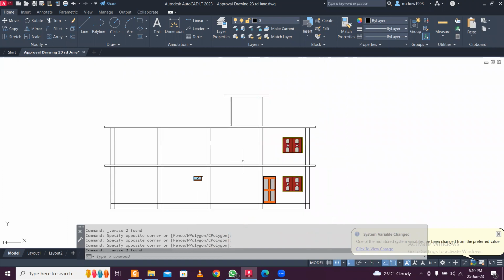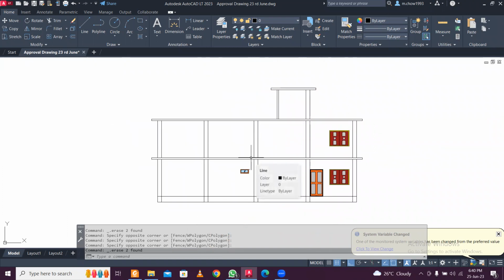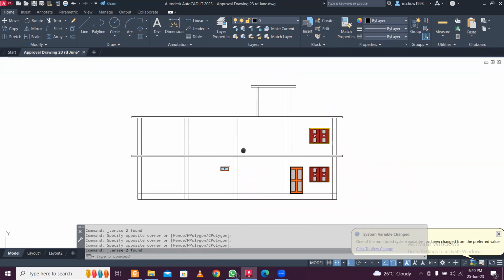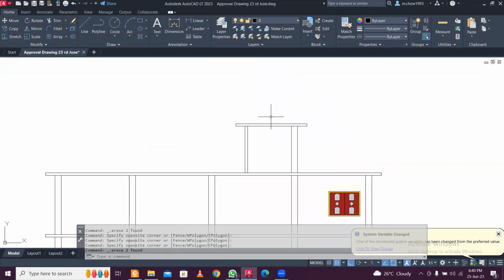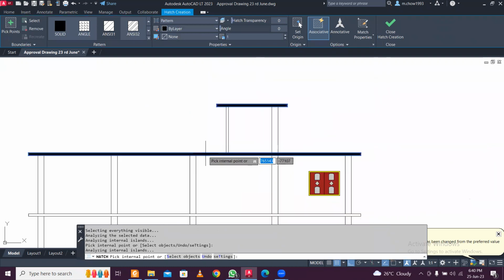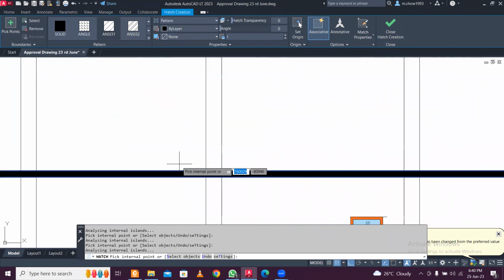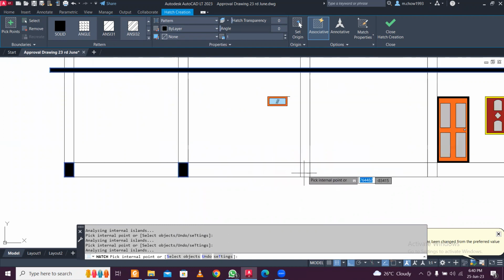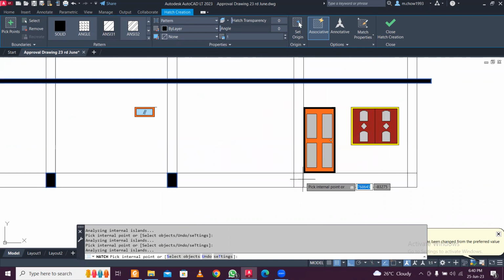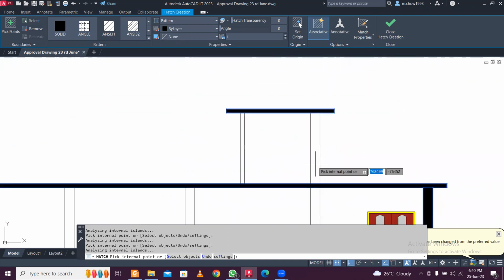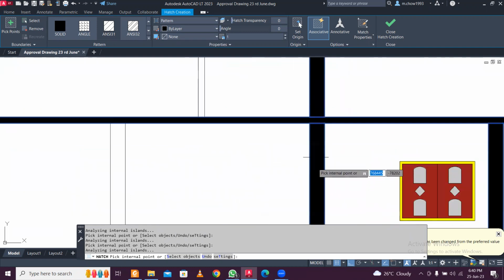So it's pretty simple. Those who have just done the drawings in the ED class, engineering drawing or the building drawing class, the concept is simple. You're doing it only in AutoCAD. So now we use the hatch option, and you can use it like this. All the concrete members, just put it on single hatch, right? Single hatch and put on the concrete members. I'm not even customizing it. I'll customize it later.